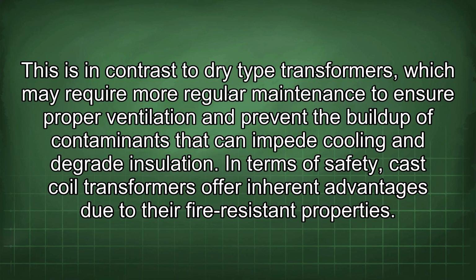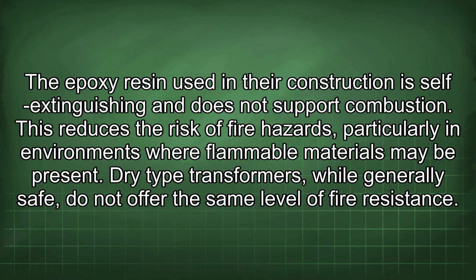In terms of safety, cast coil transformers offer inherent advantages due to their fire-resistant properties. The epoxy resin used in their construction is self-extinguishing and does not support combustion. This reduces the risk of fire hazards, particularly in environments where flammable materials may be present. Dry-type transformers, while generally safe, do not offer the same level of fire resistance.